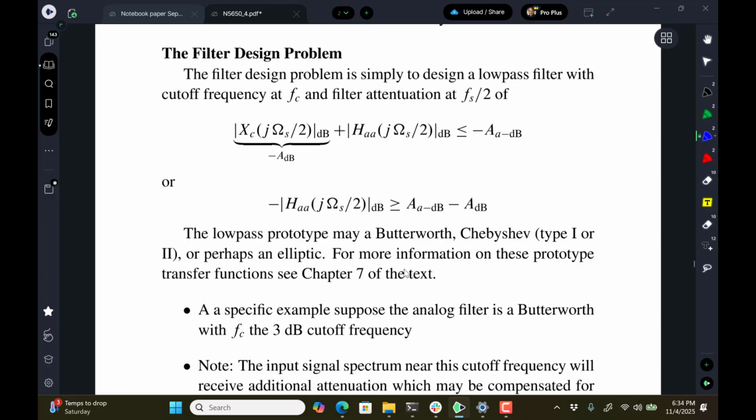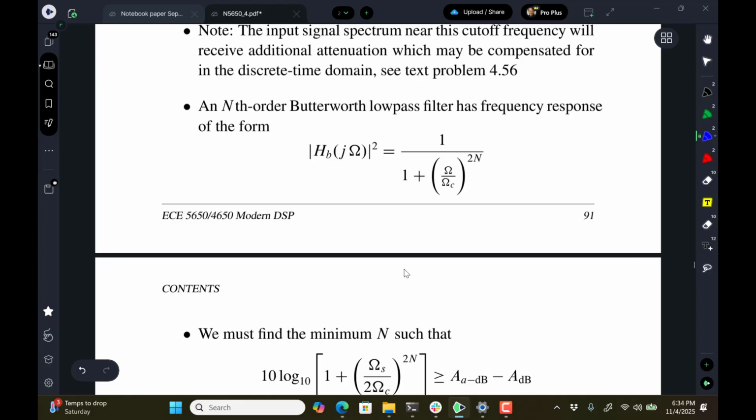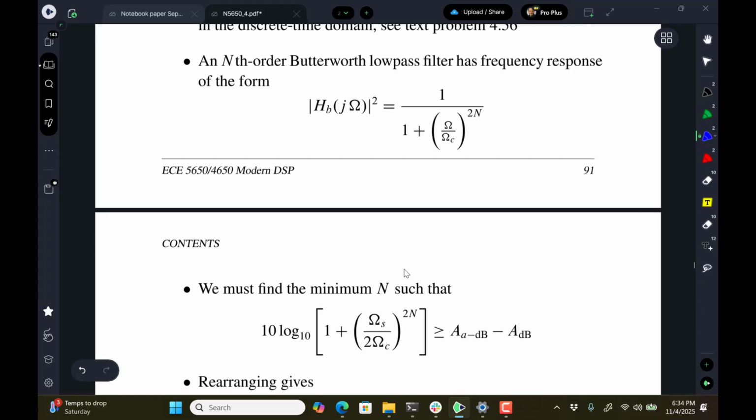And what you do with this sort of idea is, if you have a Butterworth, you can push into that analytical model for the Butterworth and say, if that's the spectrum of my signal, that's also the shape of my anti-aliasing filter. I can spin that around, just looking at the equations, and I can come up with a number.